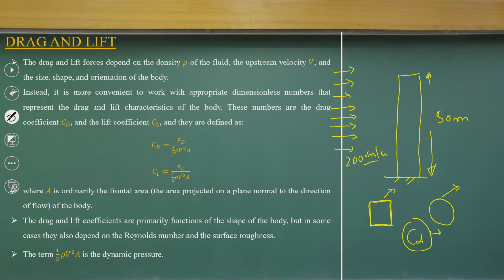You cannot say that just graphically. So, that is the reason we conduct a series of experiments and finally provide the CD values, which are the guideline for an engineer to decide when constructing a high-rise building. He has to look at whether to go for a rectangular shape or a circular shape. That is a very simple CD value, and if you can interpret how these CD value variations are there and which one will be more, just think about that.